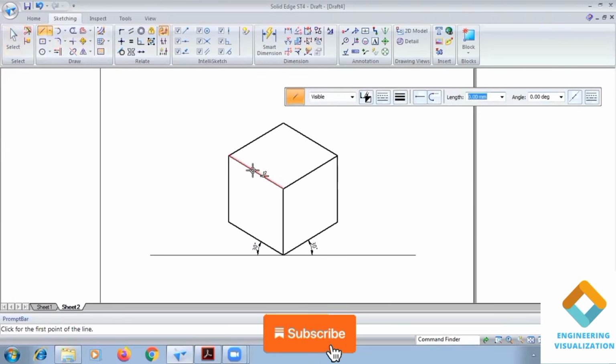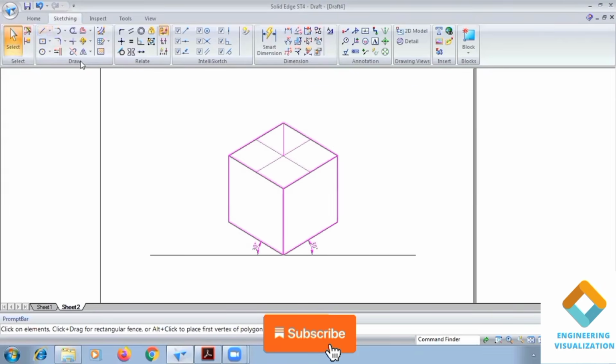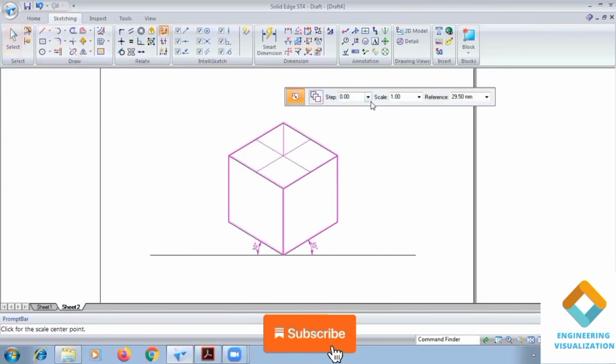Okay, so find out the midpoints. Height we need to find out. This is the center of the box. Center of the sphere will be found out. The height will be 25. Okay, now after finding out the height we will convert into iso. So this step you remember, guys. Go to scale here, type here 0.816 or 0.823, you can type it.